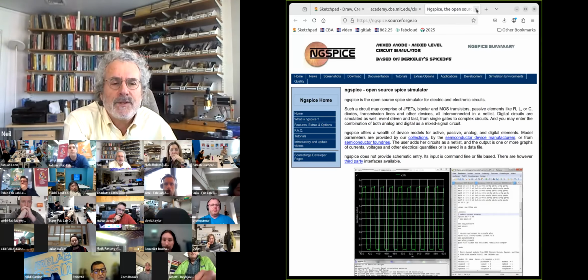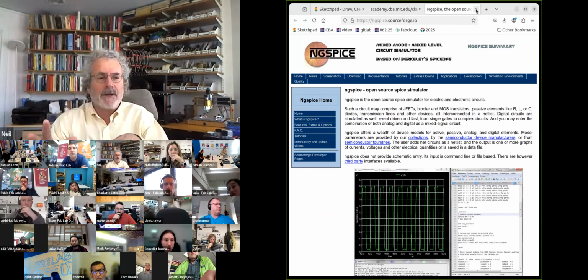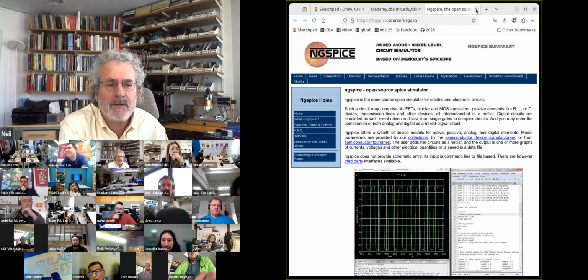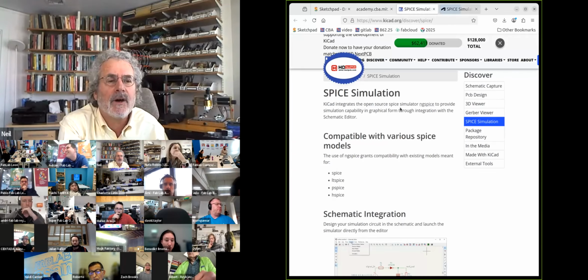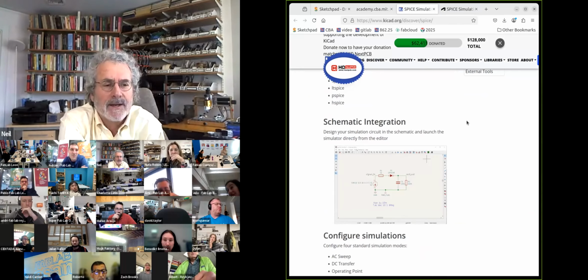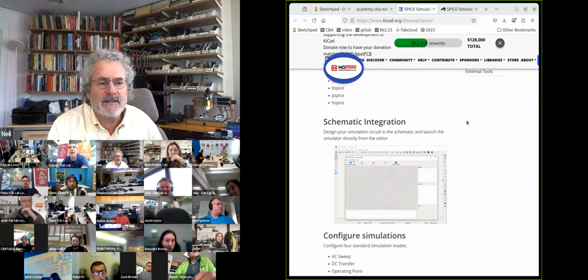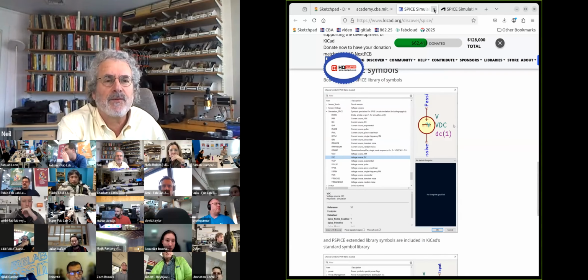The components we're using, along with the footprint, the schematic, and the 3D model, many of them also come with SPICE models that tell you how to simulate them. And both KiCad and Eagle know how to talk to it. So from KiCad, you can make your schematic, then you can go to SPICE. Now this isn't a tutorial. This is very high fidelity simulation of your circuit that you can use to study its performance.